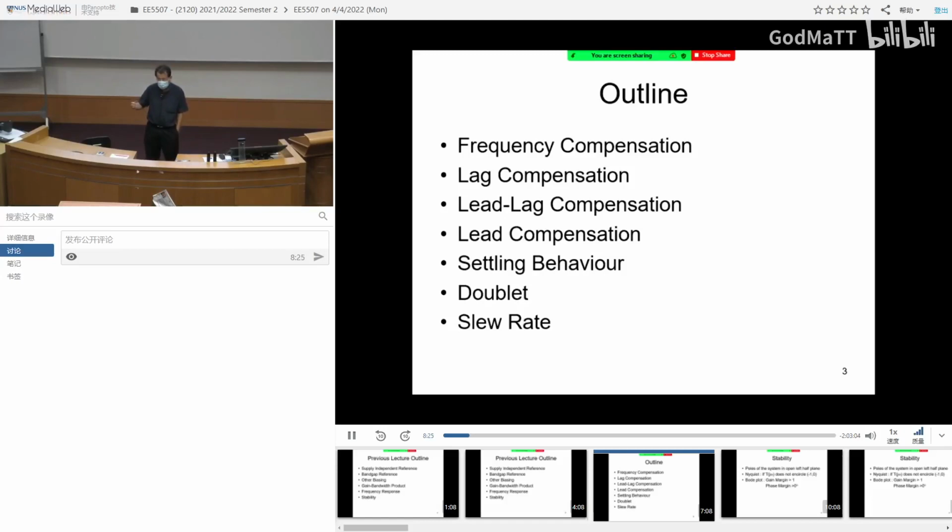Omega, you can think of it like a RC time constant. Omega for a simple passive low-pass filter is 1 over RC. Right? And RC is the time constant. So if you have a step response, how long does it take for the RC to settle? Settle to 99.9%, it takes 7 RC or 6.9 RC. Okay, so that is the link between the bandwidth and the settling behavior.